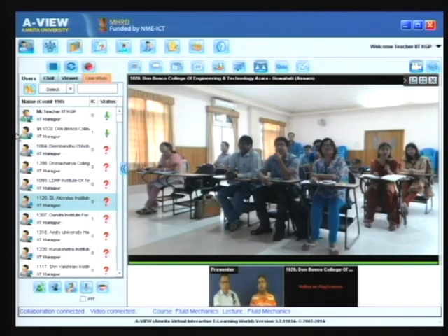No, you have to consider the total head. Many times from the total head the V square by 2g term gets cancelled as you find out the difference between the heads 1 and 2, because at the 2 points 1 and 2, maybe V1 square by 2g and V2 square by 2g are the same, so they get cancelled. So then it becomes the difference of the piezometric head, but fundamentally it is the total head and not just the piezometric head.